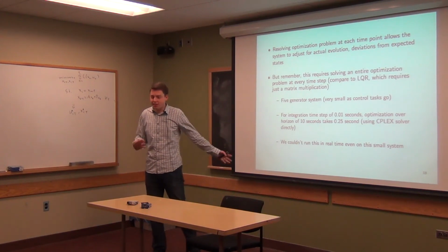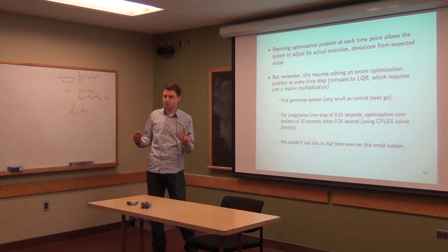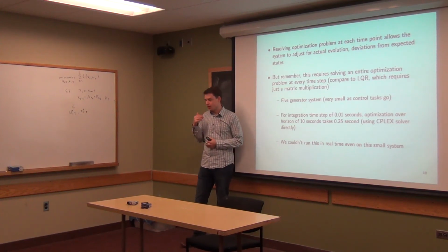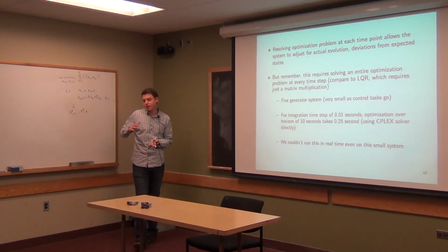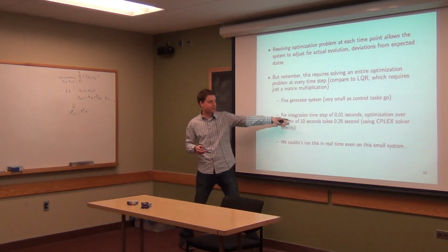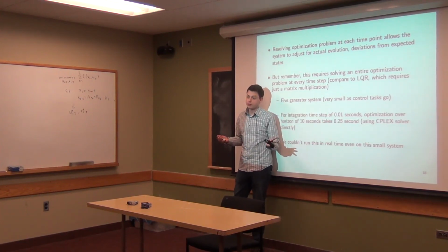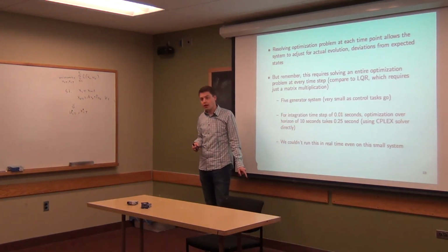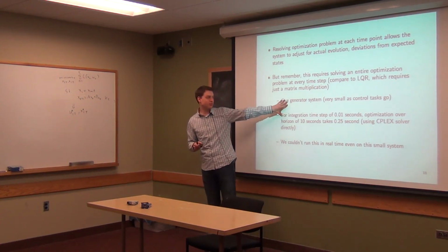So despite the fact that this might seem like a really powerful paradigm, there is this heavy cost to it. And a lot of what makes MPC actually applicable to a real domain depends on how fast you can speed it up, right? Can we get this fast enough to actually execute it in real time? And of course, that'll depend on the system you're controlling. If you're controlling a system that evolves on the order of 0.01 seconds, that might be tough to do. I'll show you how we can get there for this system, but this is still a pretty small system. It's a 5-generator system.